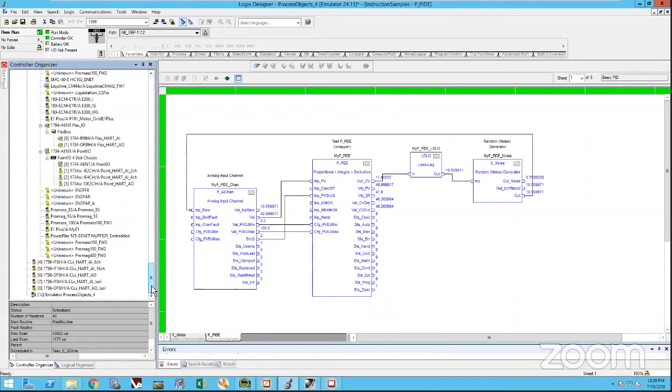Does the new emulator also support Ethernet devices, or just OPC connection? You can do Ethernet devices, but we have a differentiation between just emulation where I'm doing inhibiting, and we have an Emulate OTS now that does operator training simulation. So if you want to bring in an external simulator, it can tie into the emulation box so that you can simulate I/O. That's already out as version 24 and I believe 30, for sure 24.